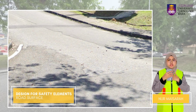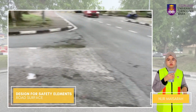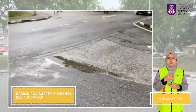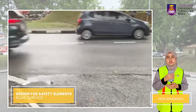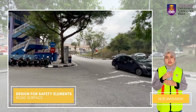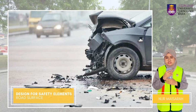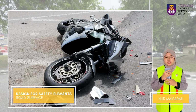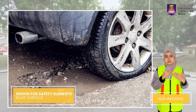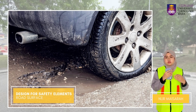Based on our observation at the road intersection, we noticed that there is a part with a damaged road surface, with road surface deterioration, uneven surfaces, and it could also cause potholes. These road surface problems are caused by the breakdown of pavement materials from prolonged usage, poor road structure, and also overuse by heavy vehicles. This could increase the risk of accidents, especially for motorcycles, and cause discomfort to drivers at the intersection. The sudden impact from the vehicle's tires approaching the potholes can also damage the vehicle's components.